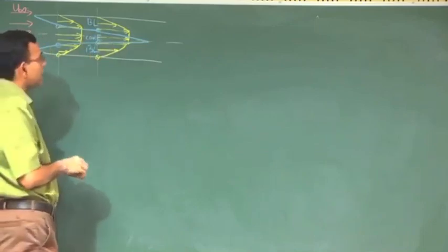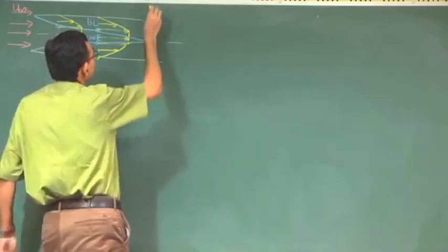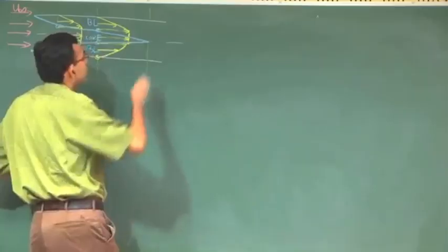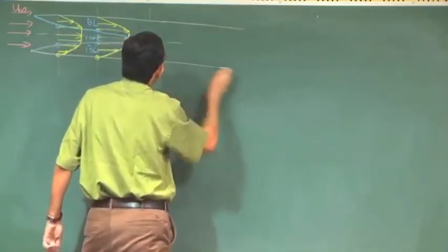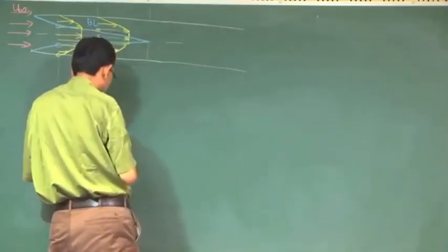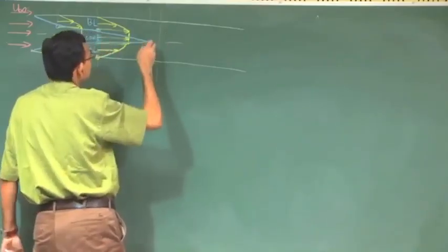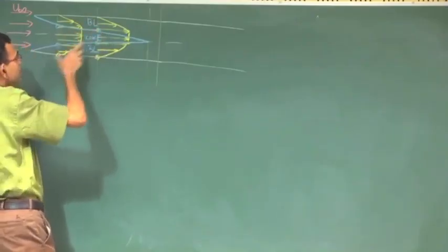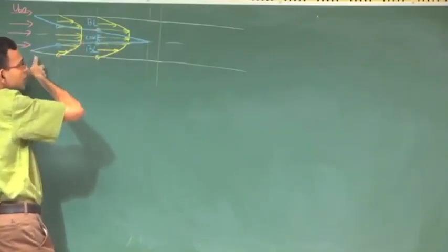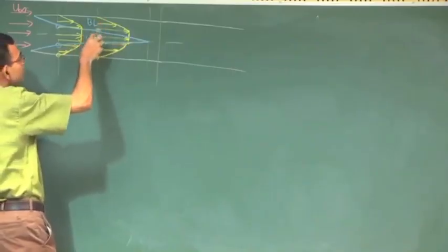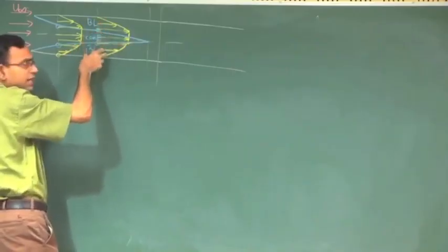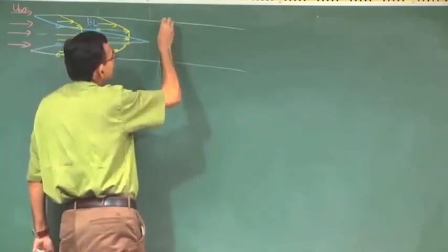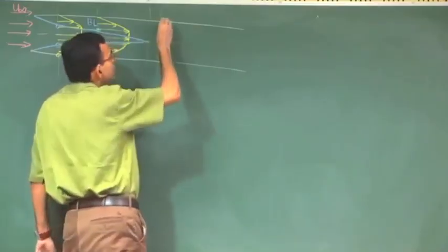When the boundary layers merge, not exactly from here, but somewhere in the nearby location, if you draw the velocity profile, then the difference between that location and this location is that in the developing region, where the boundary layer is growing, the core fluid does not understand the effect of the solid boundary, but beyond this the entire fluid understands the effect of the solid boundary.